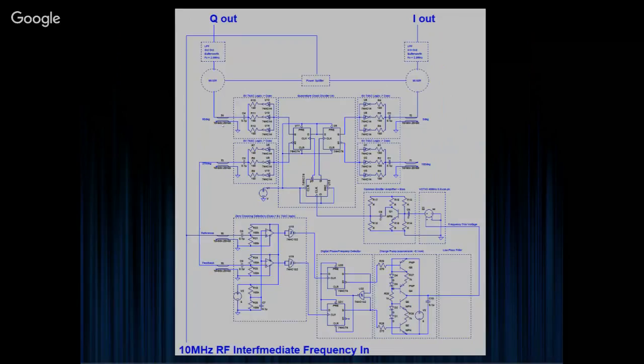That gets mixed with the local oscillator input on the mixer, which is driven by the quadrature oscillators. Then the output is at intermediate frequency. It's important to get the ports on the mixer right, because the intermediate frequency allows you to extract a DC component. That helps you very quickly and easily identify whether or not you have phase lock, because the DC component is going to be DC and not some wandering beat frequency. And then one of the signals from your local oscillator is fed back in as the feedback loop on the phase lock loop.